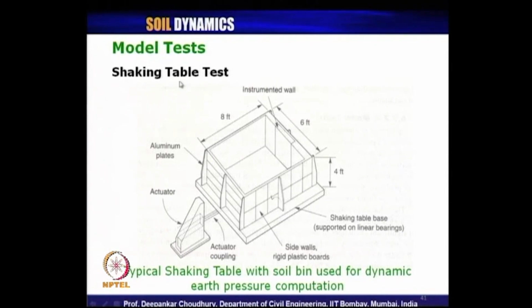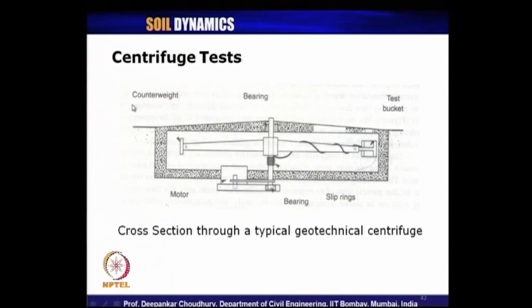So, to avoid that kind of scaling effect for geotechnical problems, the best solution is to apply the geotechnical centrifuge facility, where the stress conditions are first maintained, and then all other dimensions are obtained, so that your small model can be scaled up to your actual prototype by using a high gravity level.